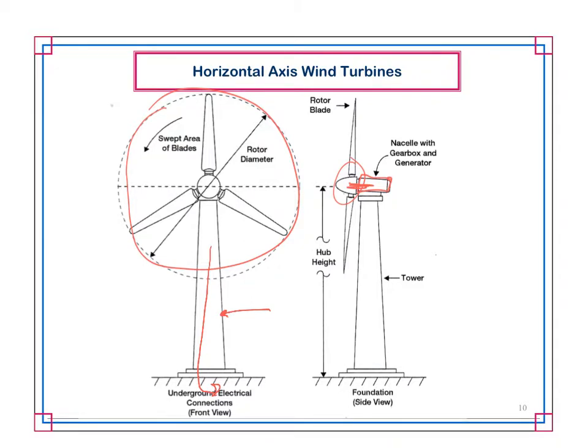So, this is kind of a cartoon showing you that it's half the height, but they usually go much lower than that. So you wouldn't want your blades to be hitting upon your electrical. So usually what happens, you have at the base of your wind turbine, and again, this is a little bit more North American specific, you have a pad-mounted transformer and a switch. All that stuff is all underground.